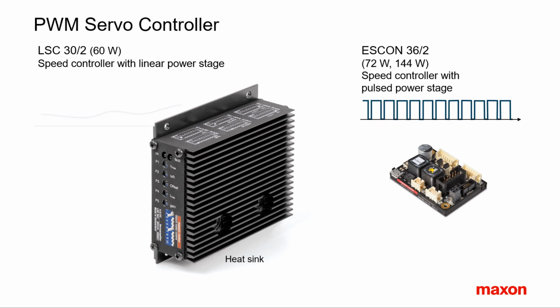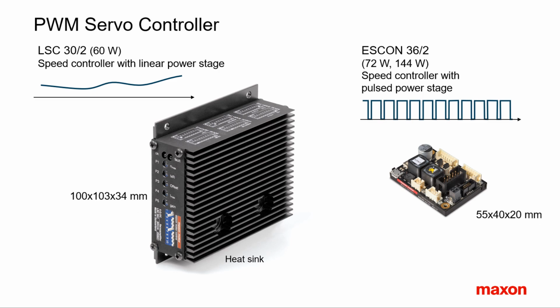As an example, let us compare the size of an older LSC speed controller with linear power stage to the size of a newer SCON servo controller with pulsed power stage. The pictures are approximately to scale. The dimension of the LSC servo controller is much larger, essentially dominated by its huge heatsink. Observe the additional built-in inductances of the SCON. The function of them will become clear in the following.